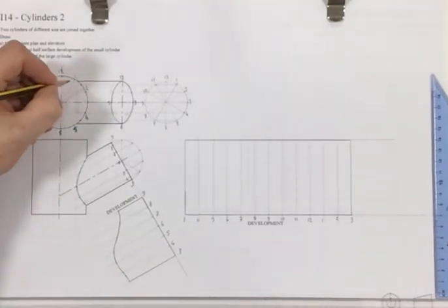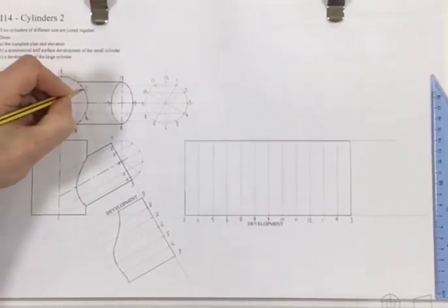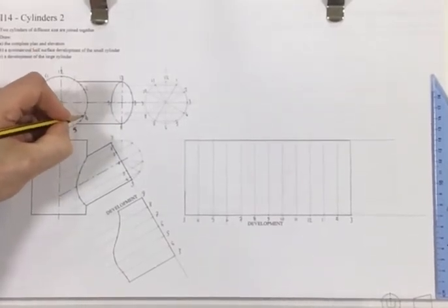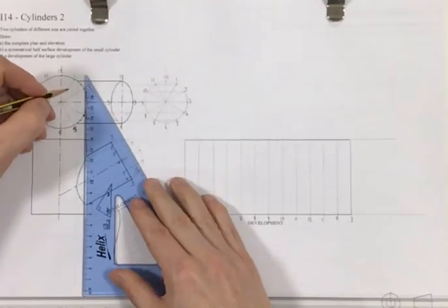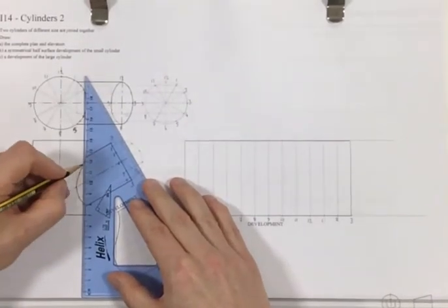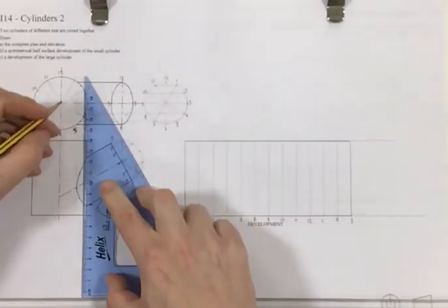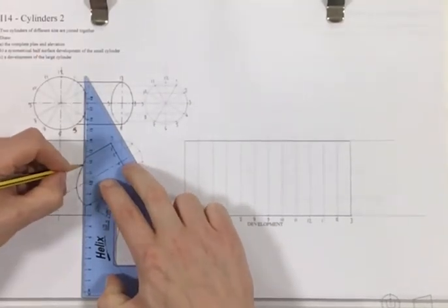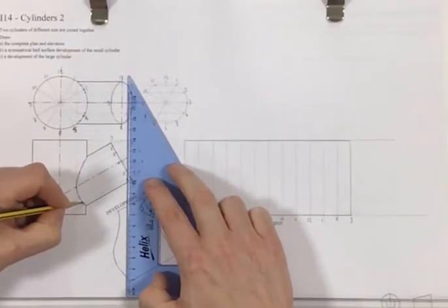And what we can do at that point is we can take points that we actually know. So we actually know where points 2, 3, and 4 feature. Okay, 2 is there, 3 is there, and 4 is there. So we can bring those down onto this drawing, which will give us the heights that we can then project across onto the same numbers. So there is point 2, so we can bring that down to there, where it cuts through that, and there as well. Okay.